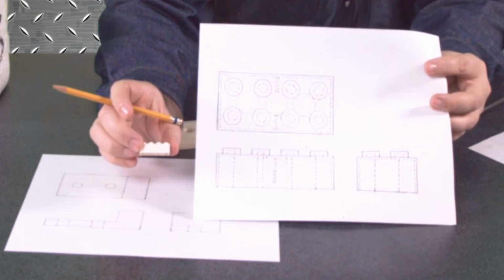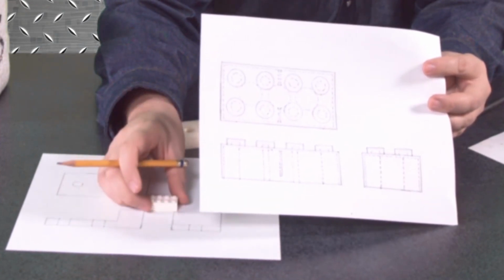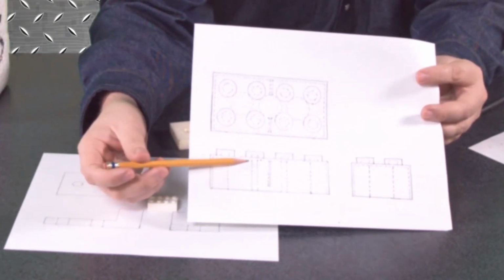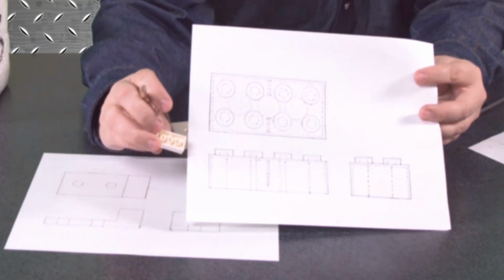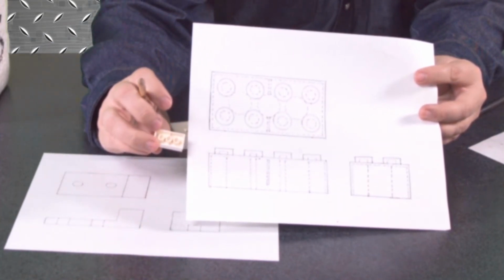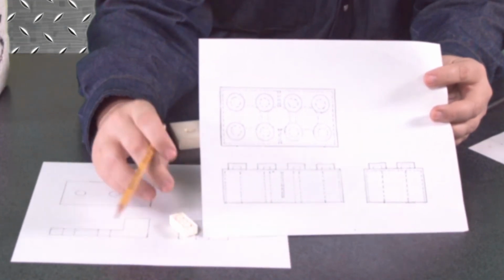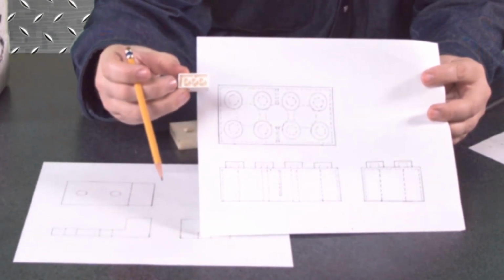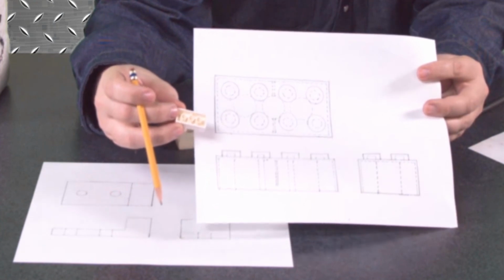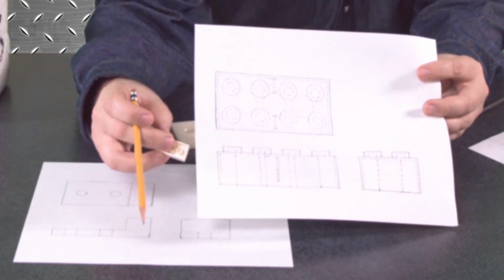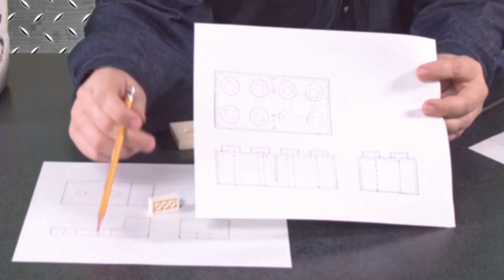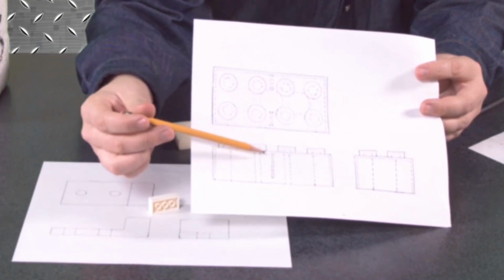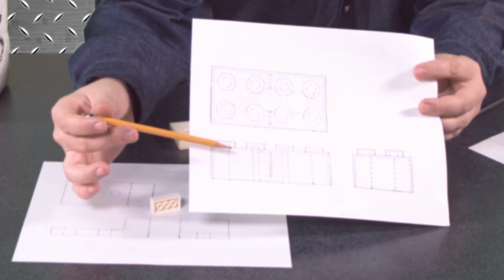Now, from the front view, you'd think there's not much there. Well, once you add in the element of hidden lines, you can actually start to see, because if you view it from the bottom, you'll see there's 3 cylinders on the inside of there, and further inside of the piece, the studs that come out of the top have little dimples inside of them as well. And then there's these 2 support structures right there. Now, I've drawn them all out as hidden lines on the inside to see the orientation.